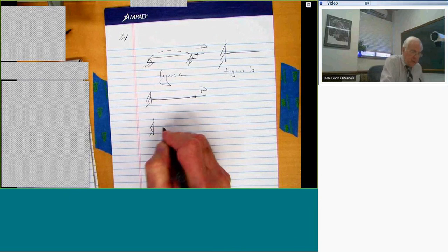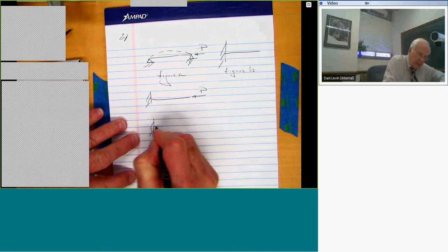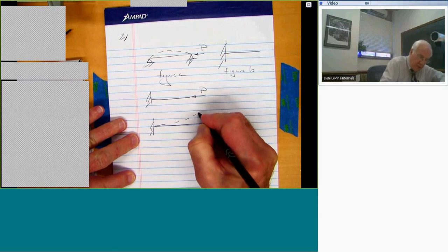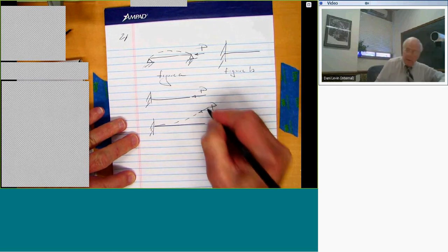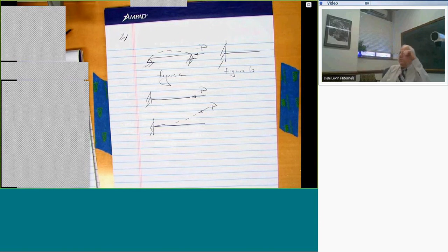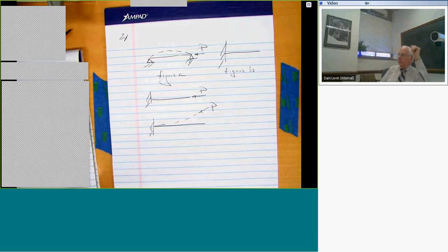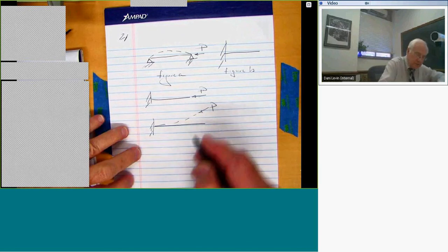There's a different problem, which is the following. Now I let this deform in some way. If I assume that this force follows the deformation so that it is always aligned with the local slope, this will not undergo a static instability. It, in fact, will undergo what an aeroelastician would call flutter. This is the so-called follower force problem.